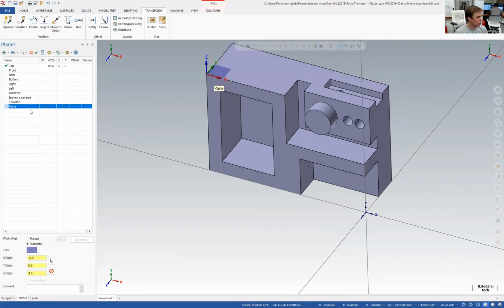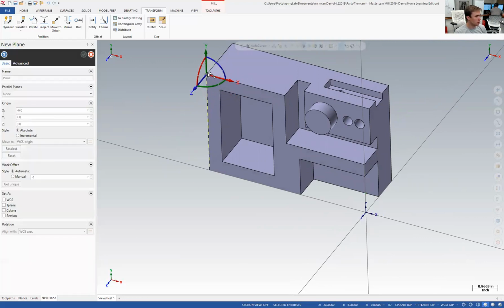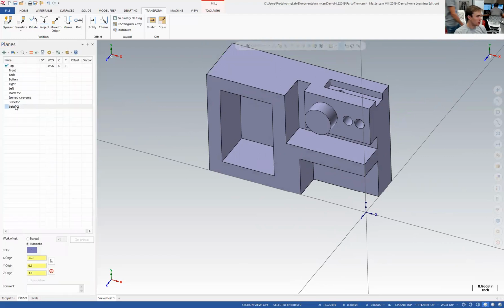I forgot to show you. Let's do that one more time. Delete, start, click, rotate -90. Okay, over here in this sidebar, before I hit enter or green check, you can name it. So maybe I name this setup 2. And then we can hit check. Now it's whatever you want it named.